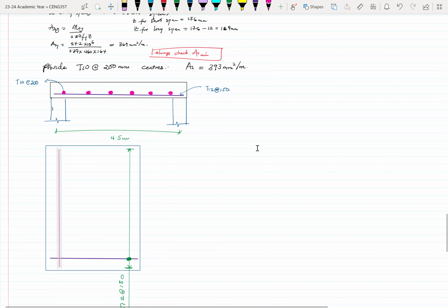now we also have this bar, and let me increase the thickness of it. So we can have this bar here, and then we do another line, maybe just somewhere here. Now this color is the bar color, so let's go with the red. This is where they intersect. So basically it's a rebar and then the indicator lines. The red here is the indicator line, and the pink is supposed to be the rebar. So this is where the bar ends. Then this becomes T10 at 200 millimeters.